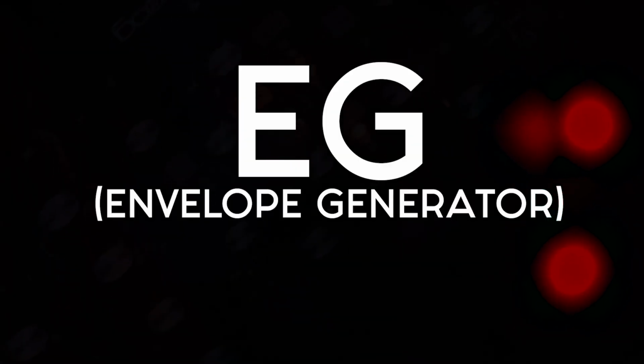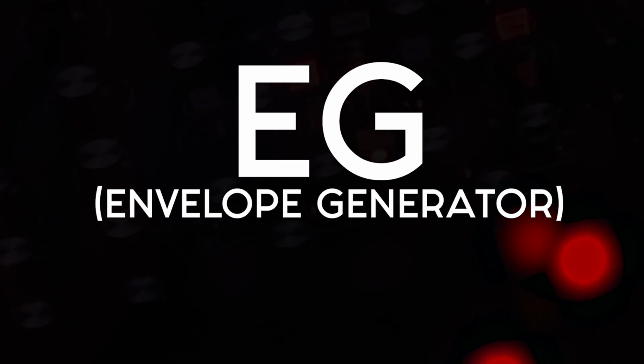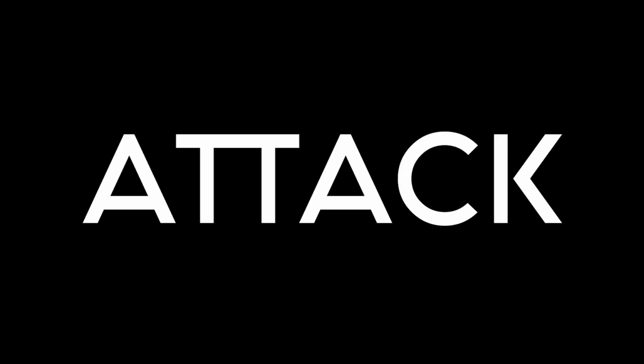We need to add another module now called an envelope generator. This envelope generator will use 4 stages to shape our sound: attack, decay, sustain, and release. Attack is how we first hear the note. It's how long it takes to get it to its max volume. A fast attack means we'll hear the note immediately.